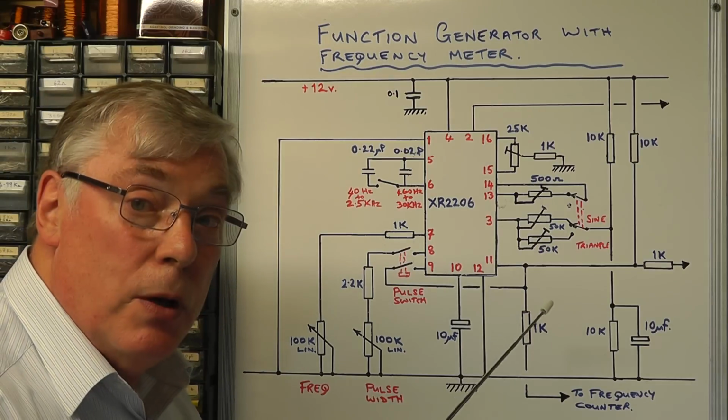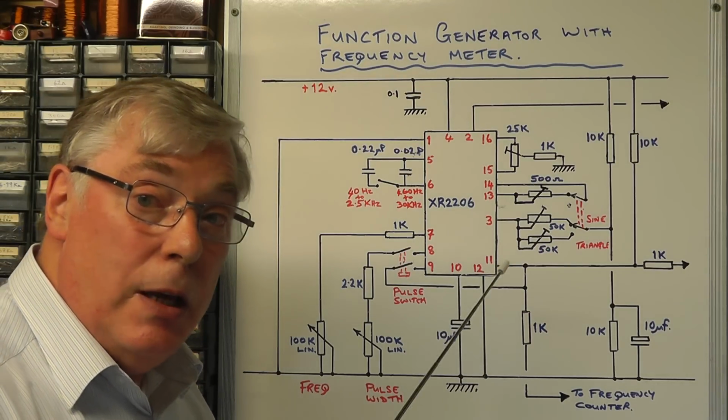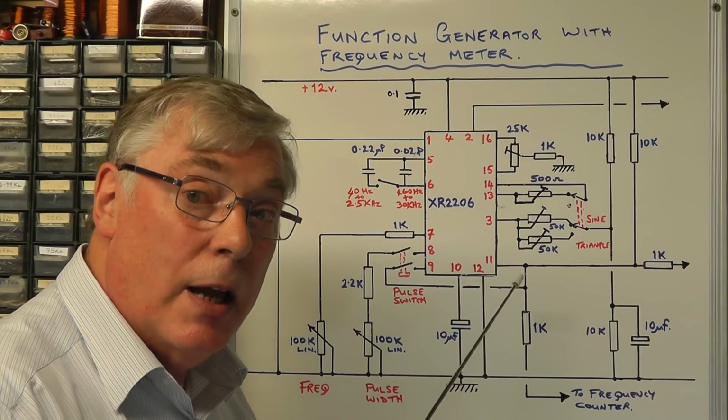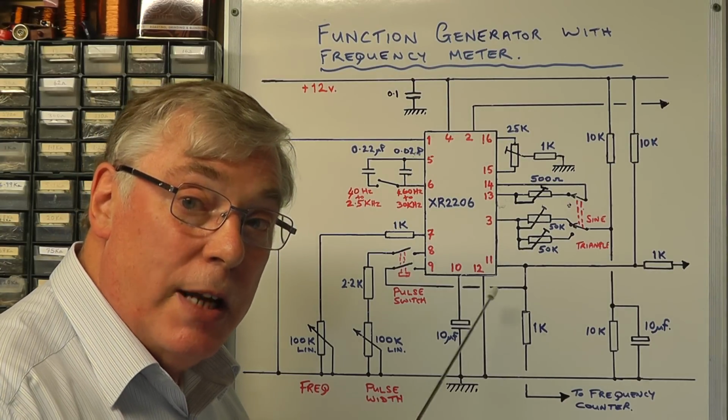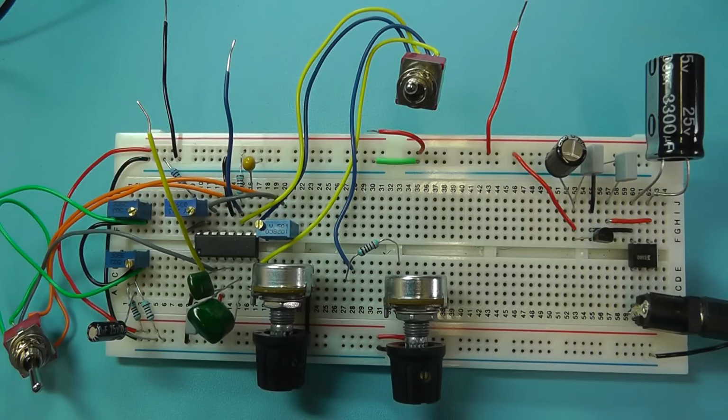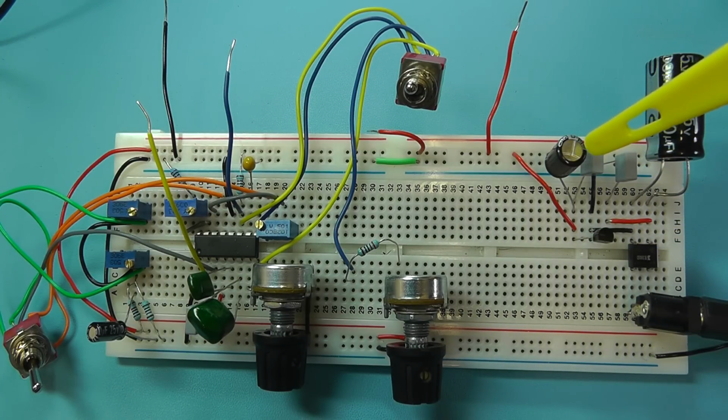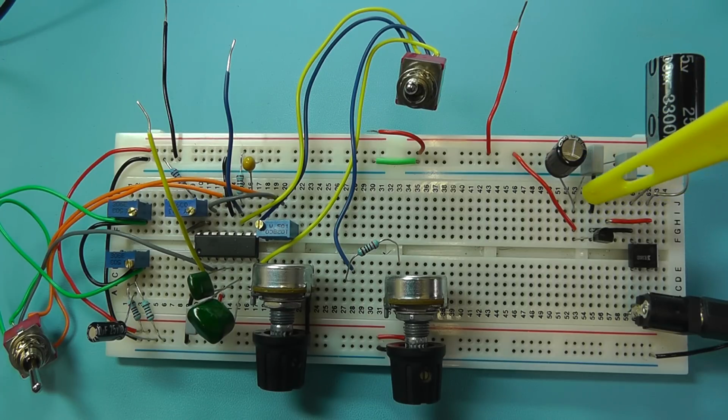What we'll do now is build this circuit together with the power supply that I illustrated earlier onto a breadboard, and we'll test this first. Right, here you see we've laid out the circuit so far on the breadboard. There's the power supply, 9 volt AC coming in to the bridge rectifier, the 3300 microfarad smoothing capacitor on the output of the bridge, and then the 12 volt regulator IC, the 78L12, with capacitors either side, and 100 microfarad smoothing on the output of the 12 volt regulator.